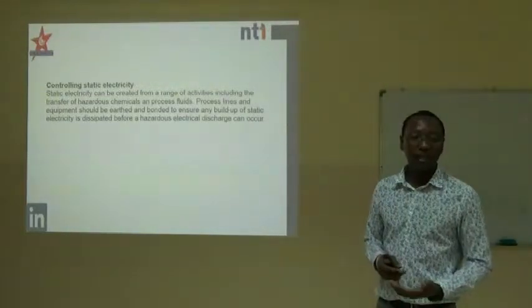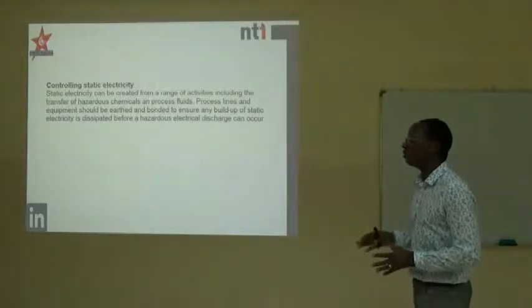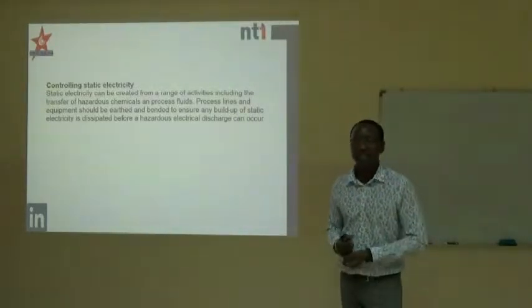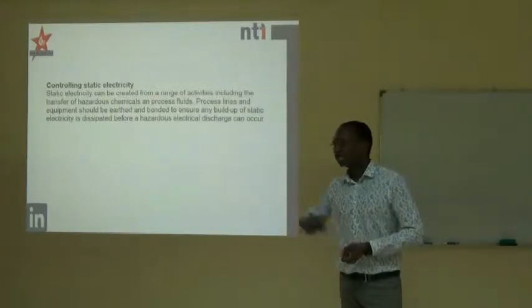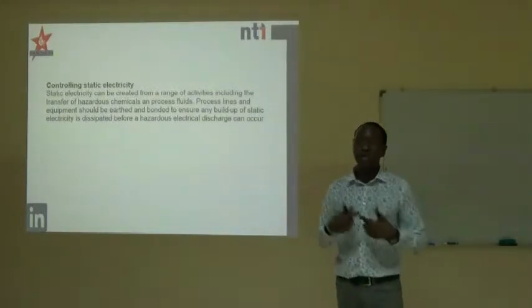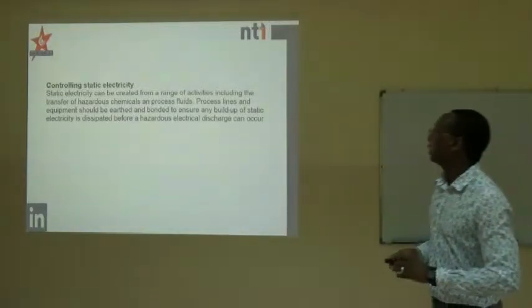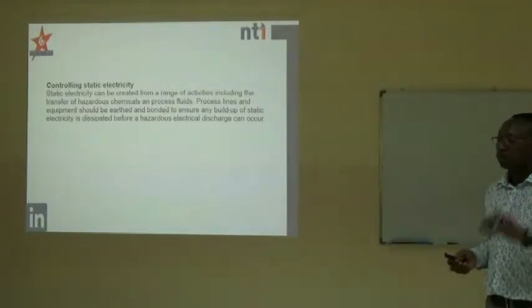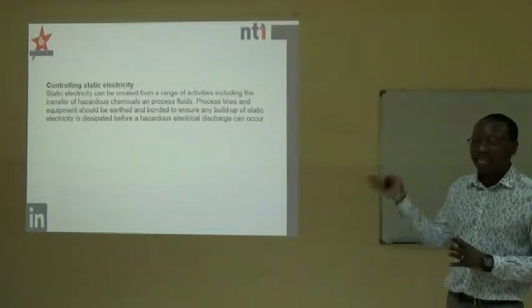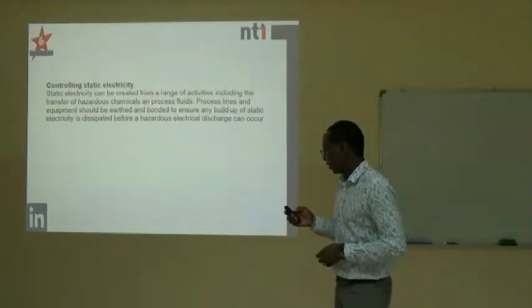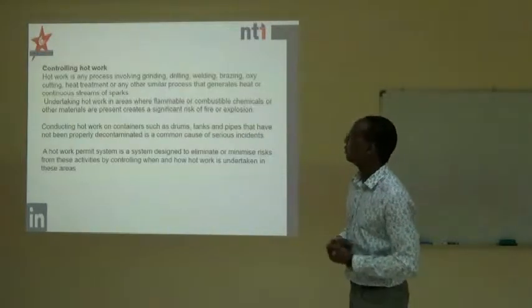That's bonding. If you have been looking in your homes, you have seen that if you've got water pipes that are metal, if you've got gutters outside, they are normally bonded. They are joined to the general mass of the earth through these copper strips. So while we are doing that, we are trying to create a path for any leakage currents to go to the general mass of the earth. Okay, so we can move on.